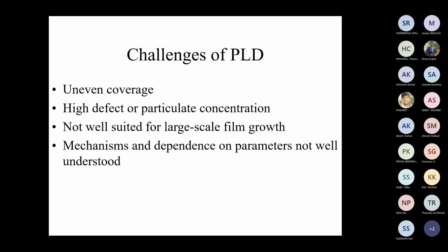But still some challenges are there, like uneven coverage and high defect or particulate concentration. If the ablated particles come directly, of course, it will not give a smooth film; it is uneven, that's why the coverage problem comes. With particulate deposition rather than atomic deposition, the defects will be more, and it is not well suited for large scale film growth.